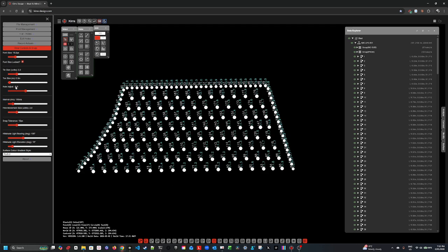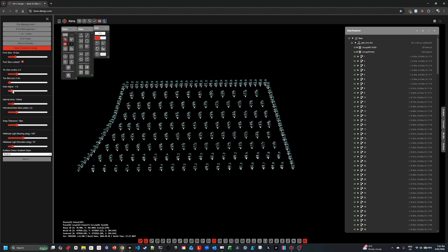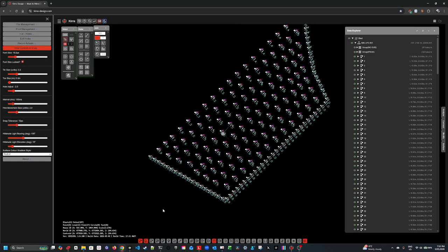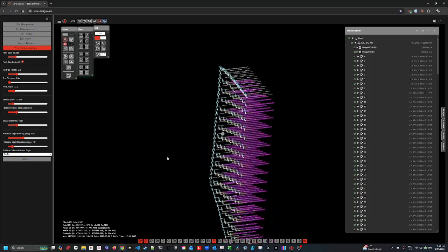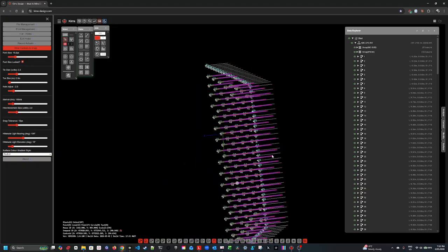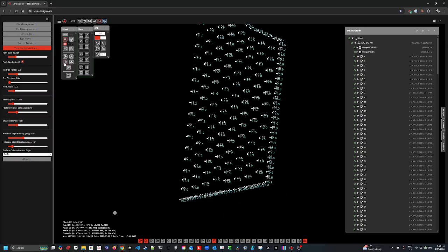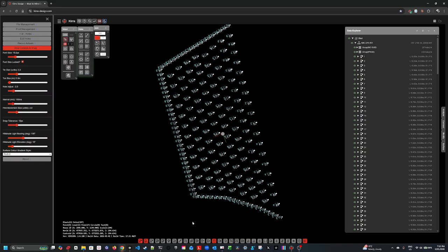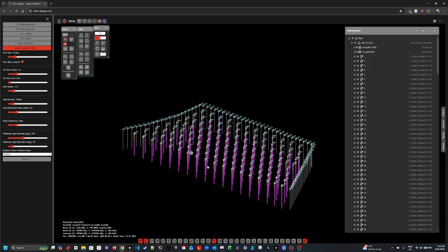And we can dial this hole size down to 2. Yeah. And rotate that around. You can see the charging there. The reason why it's playing up like this is because we had shift rotated it, and so once you're in there, you've got to move it back, like reset the view.